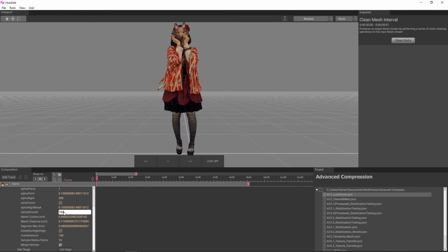Alpha smooth. Alpha smooth weights how important it is that a given portion of the mesh moves similarly to its neighboring pieces. Smoothness captures the idea that connected elements tend to move like their neighbors. You should relax this value if there are small, local deformations in the surface over the course of the motion. Like alpha rigid, this value progressively relaxes, so surface details may not vary significantly when this setting is tweaked. Generally, reasonable values are between 10 and 100, but values at 200 or more may be appropriate for captures with a lot of cloth or soft surfaces, such as our example clip.